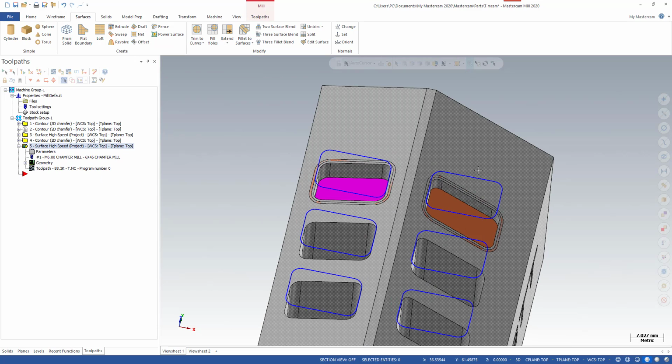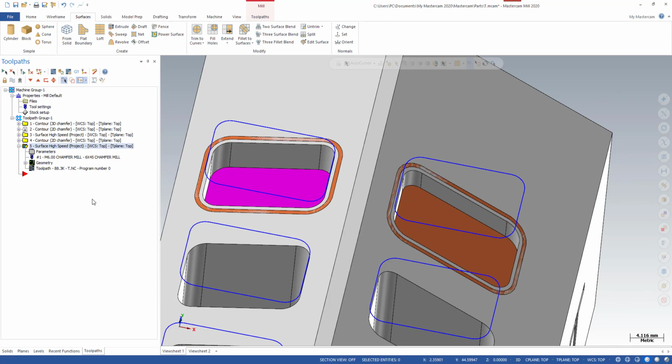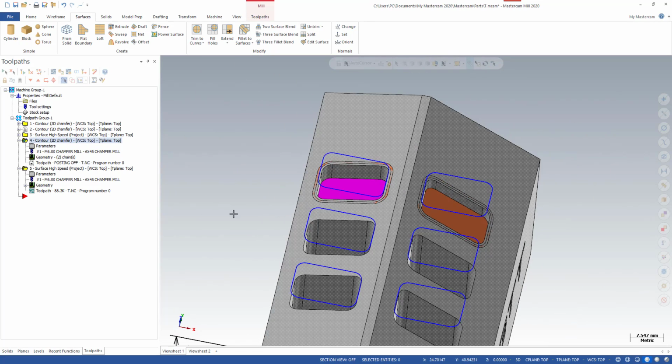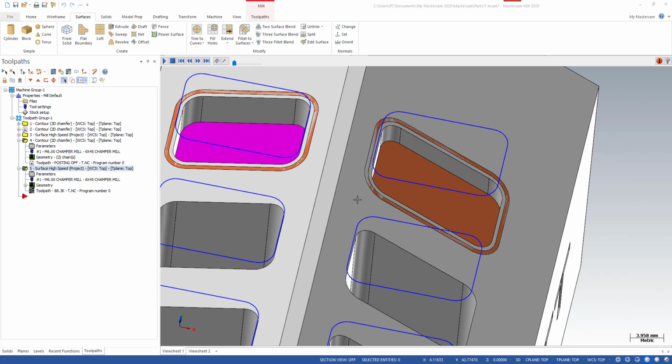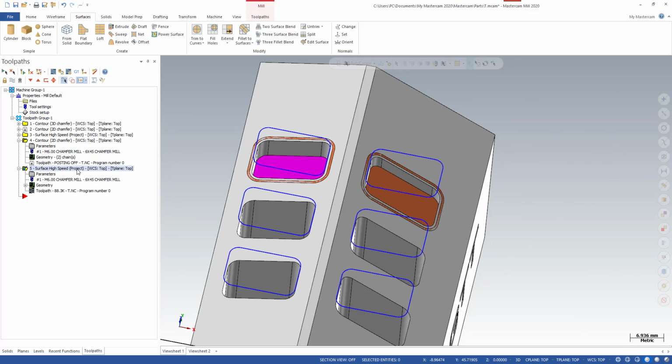And so that's the trick. You just select a project toolpath with the same tool as this toolpath. I call this the original toolpath. Normally I will ghost it, so we are not going to pause it when we run the program. We just run this one, and you can see it uses the same tool, 6mm chamfer, and this is a project toolpath.